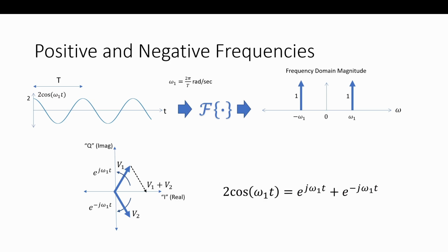We see this here on the cosine wave versus time. This is another way that we can view a time domain waveform on an IQ plane, right? So we play time forward, and the dot, that's the sum of these two phasors, would land here, and it just moves back and forth on the real axis. That's how we would see it if this was playing forward in time. Just another way to represent it, but very handy. And I decomposed it into each one of those components.